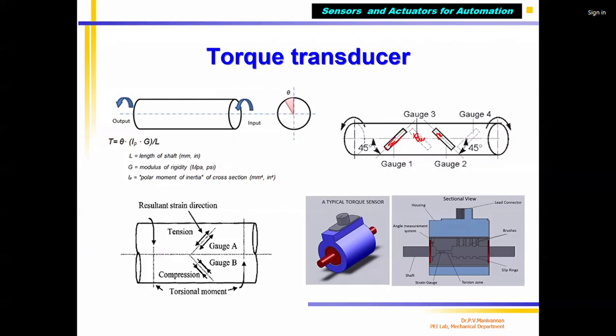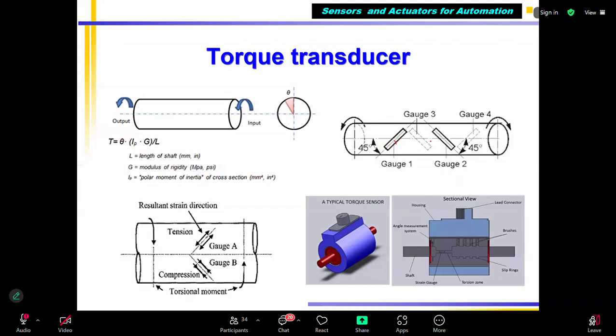So 4 strain gauges put. Depending upon quarter bridge, only one you will put. Half bridge measurement you will put 2 like this. If the full bridge you will put 4. Correct. This side, the opposite side, you consider dotted lines. Exactly opposite. The shaft is here in the cross sectional view. Correct. This is the front side. This is the back side of the shaft.